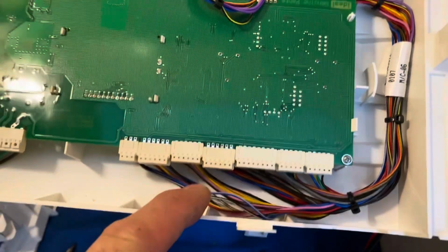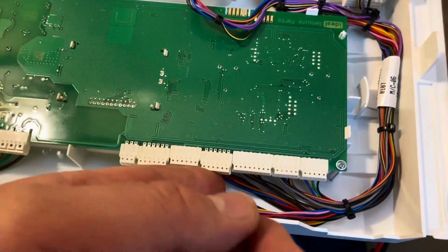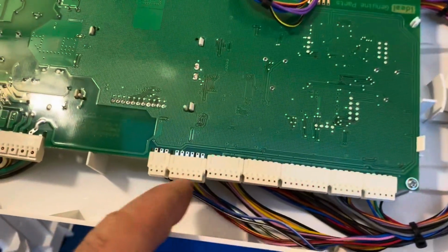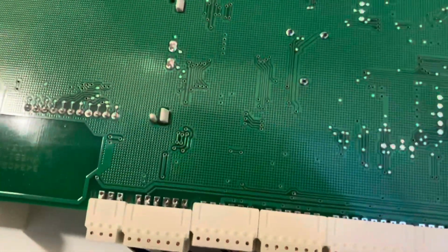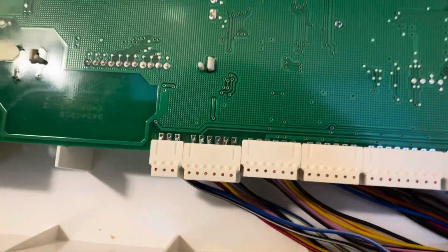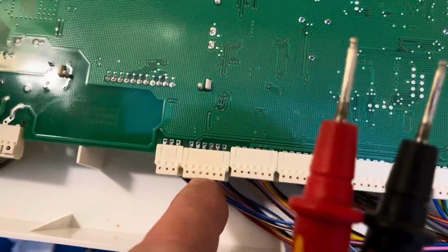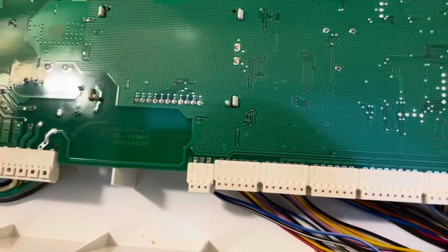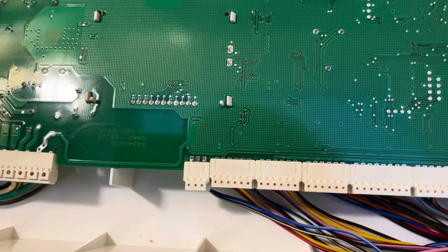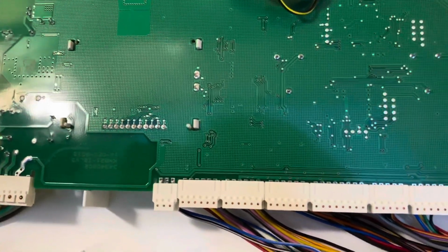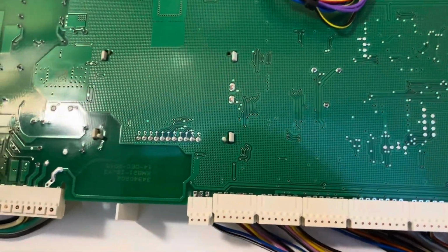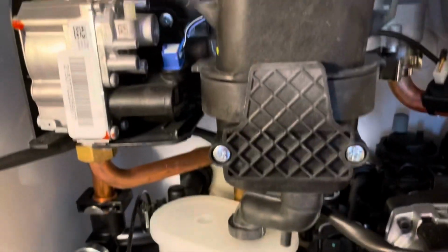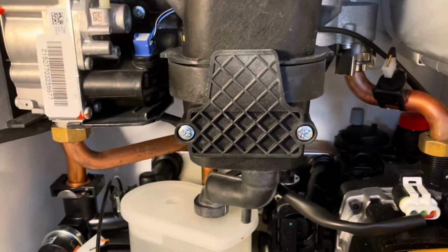Next one, so that's the low water pressure switch. This is the stepper motor, and this is the gas valve. I'm not gonna do the stepper motor one because I've done that on another video, and it's going to be difficult to do testing the cores individually. I really need two hands for that. I should be able to show you this gas valve one. So like I said, it's a 24 volt gas valve. We know we've got 0.2 amps running through it.